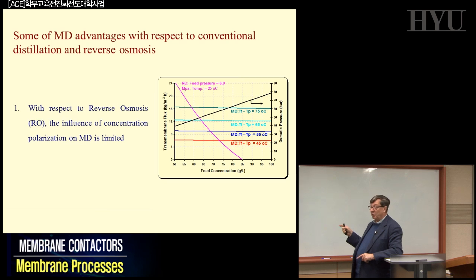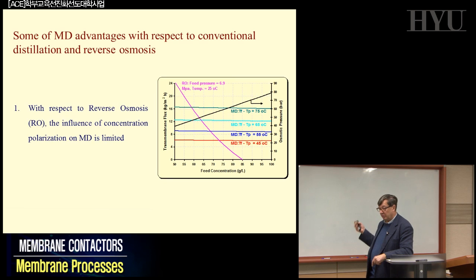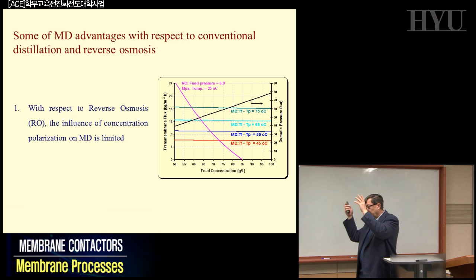So that's the reason for which, if you want to improve the recovery factor of a distillation system, today the best we can have is using reverse osmosis. Forget traditional distillation, where the recovery factor is about 15, 20%, 30% with a lot of complicated engineering. In reverse osmosis, we can already approach about 50%. In some cases, if you introduce nanofiltration upstream, that means reducing bivalent ions, you can increase the recovery factor a little bit.